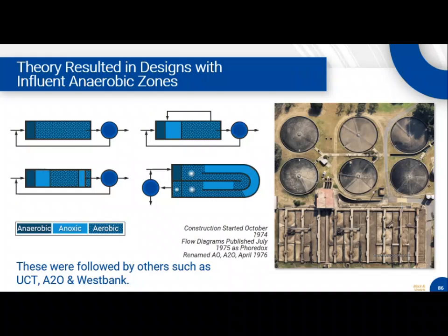What are we consuming the nitrates with in that anoxic zone downstream of the anaerobic zone? How do we get rid of nitrate? What are we pairing with nitrate? Let's move away from my broad analogy. It's just BOD, right? Yeah. BOD, nitrate, it gets removed. Essentially here you're using the other pieces of BOD.